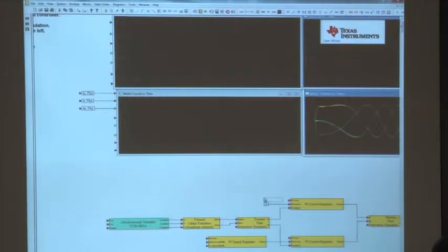So I'm going to put it on the input of the PI current regulator. I'm going to do another Control-V, put it on the other PI regulator. Where else did I need it? Oh, the speed loop, Control-V. Okay. Once I've done that, connect from the output of the sample signal into the inputs of those execute pins, as I've done here. So now those software routines know when to run, which is synchronized to the PWM module.